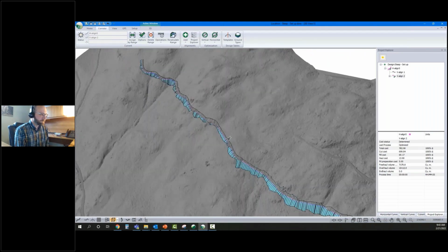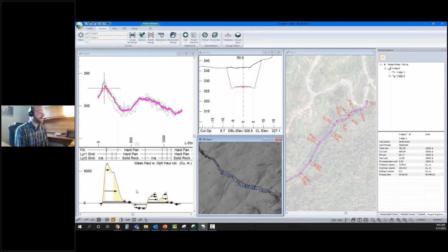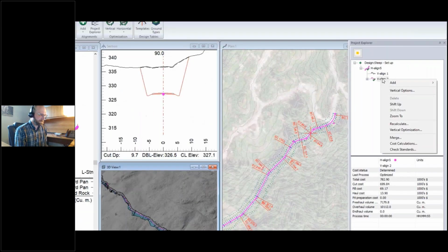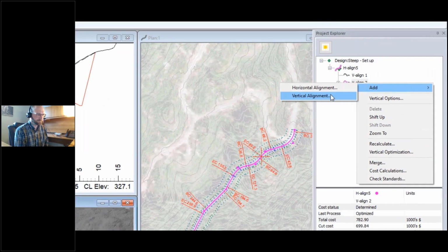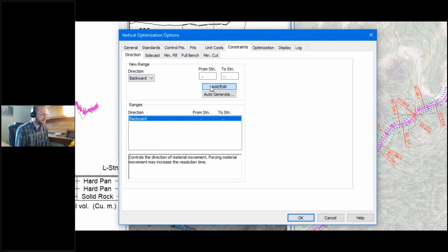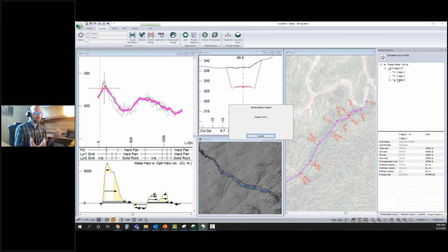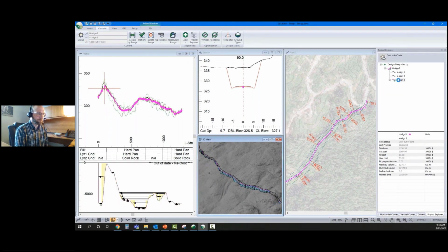Now, after that, we're crossing some pretty rugged terrain, steep, rocky terrain. And as designed right now, just looking at the mass haul diagram, we can say, okay, that doesn't make any sense. Because we've got a forward material movement on really steep side slopes. And as Jeremy said, you could stage that, or maybe you open up access with a tote road, but oftentimes it just adds unnecessary complexity when you could consider that in the design phase and avoid it.